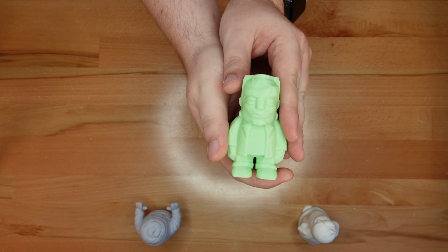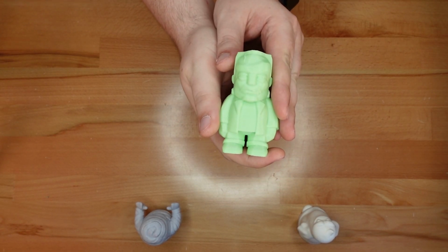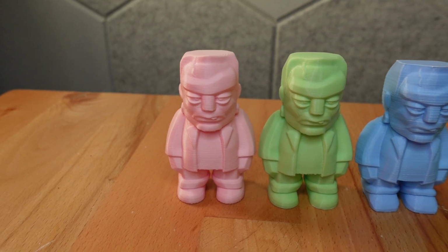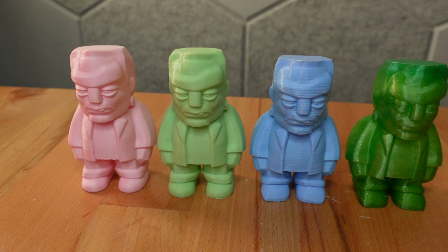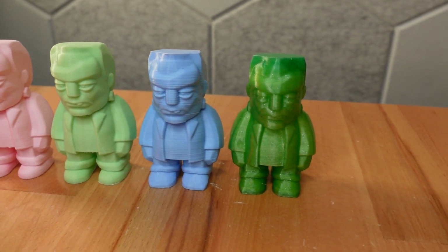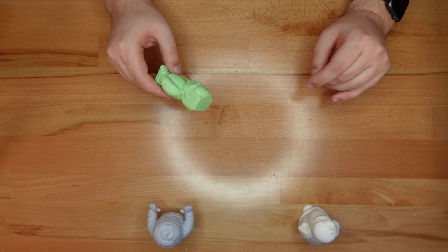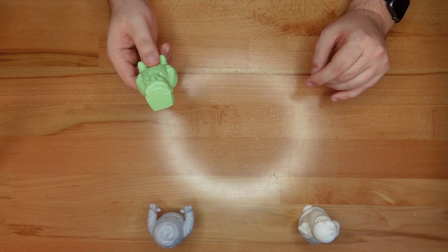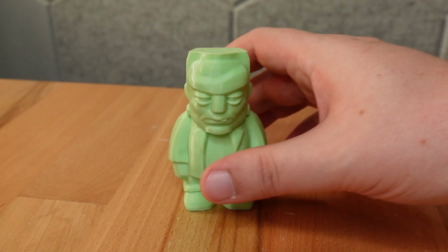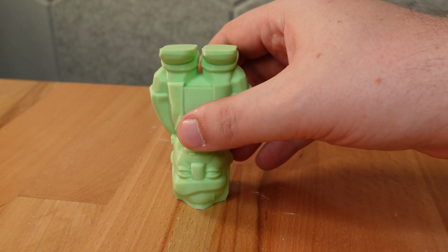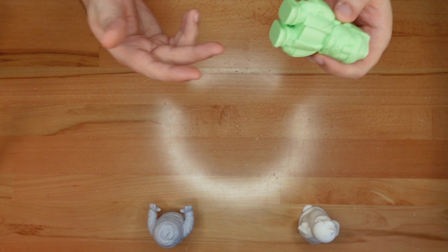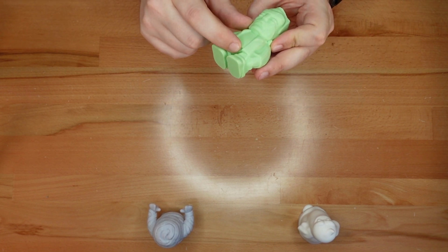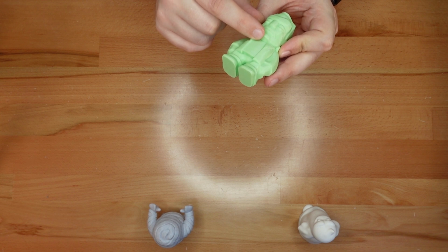I'm back with the print, or maybe I should say, a whole bunch of prints. Over a half-dozen revisions, I slowly updated the model to make it easier to 3D print. And I'm happy to report that with the right hardware, this final version can be printed without any supports. You just print the design on its head. You can print it right side up, of course, but if you do so, make sure you add supports under the jacket and under the chin.